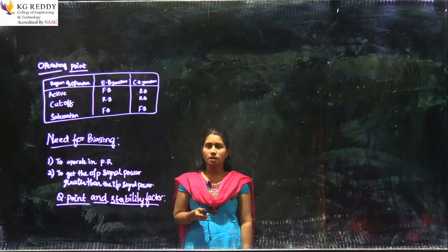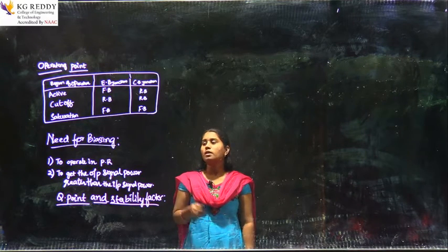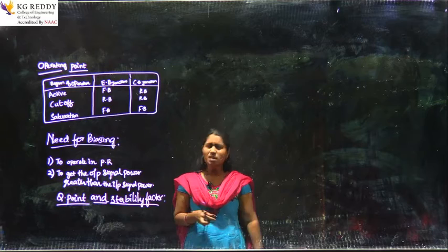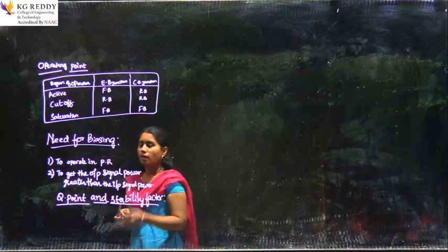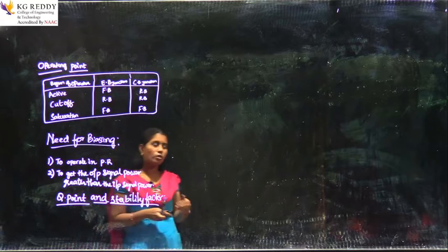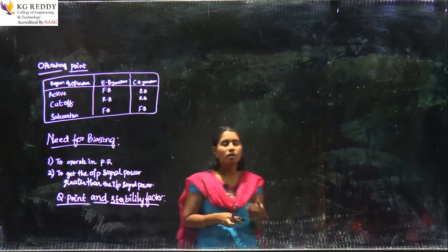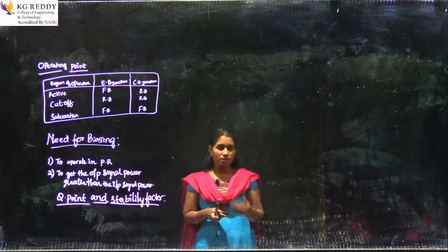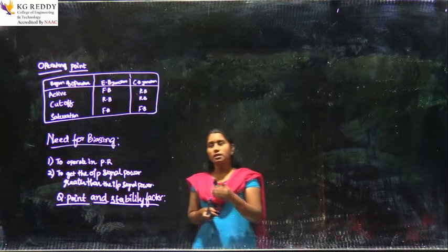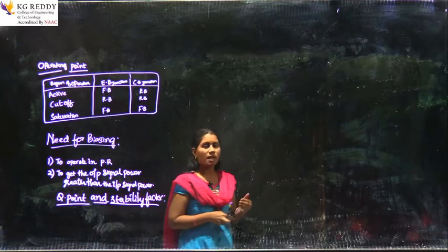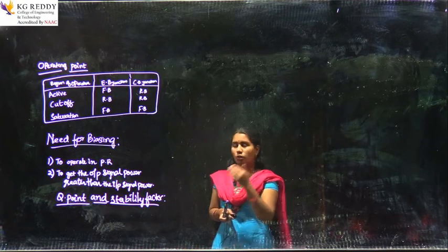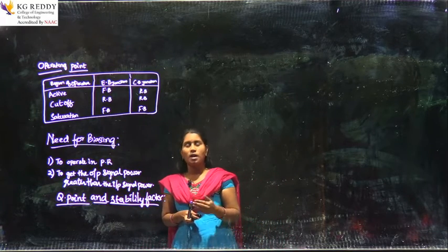That voltage and current are the DC operating conditions. When plotting the AC and DC characteristics for a particular transistor, the intersection point of the AC load line and DC characteristics is your quiescent point or DC operating point.